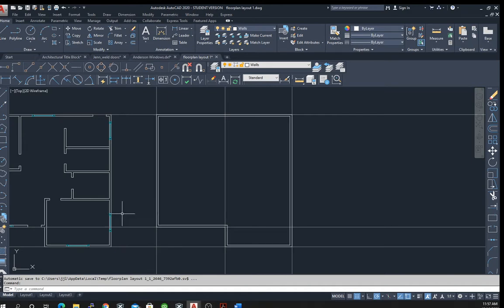So again, we'll leave 10 feet in between these drawings. So start, actually, yeah, we can just do offset. So we'll type 40 feet. Alternatively, we could have chosen this line and done 10 feet. It'd be just as fine. We choose this line.